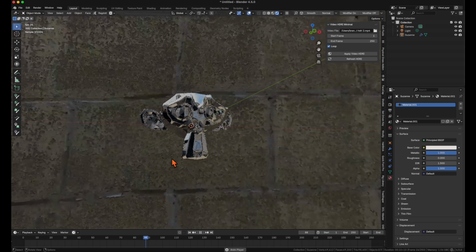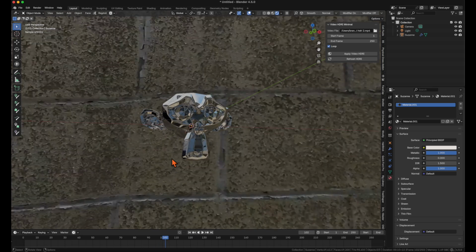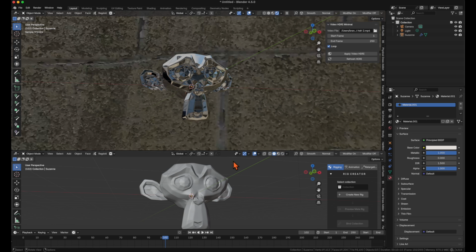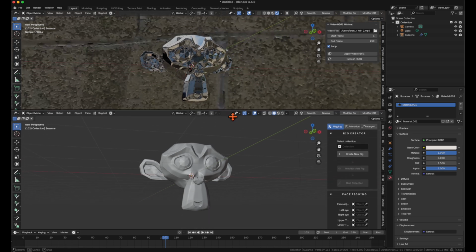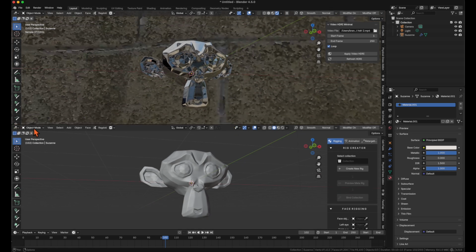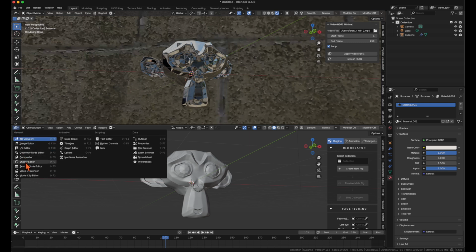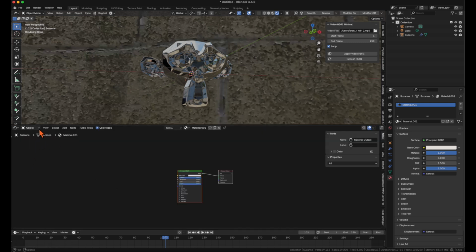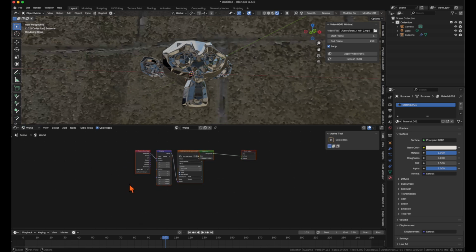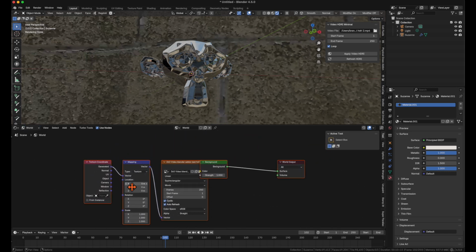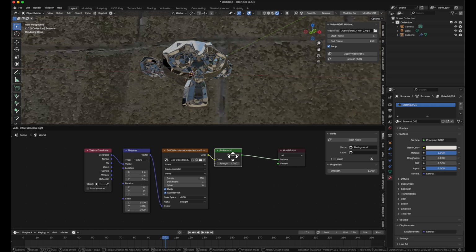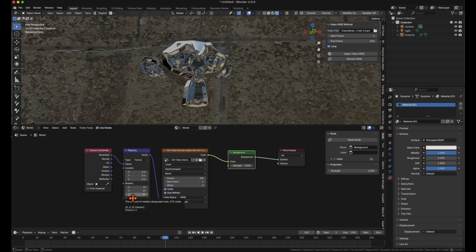And now I wanted to show you that you can actually change the rotation of the video HDRI. So you just bring up a new screen in Blender, then go to your shader editor. You go to the corner where it says object, change it to world. And now you can see the Z rotation.